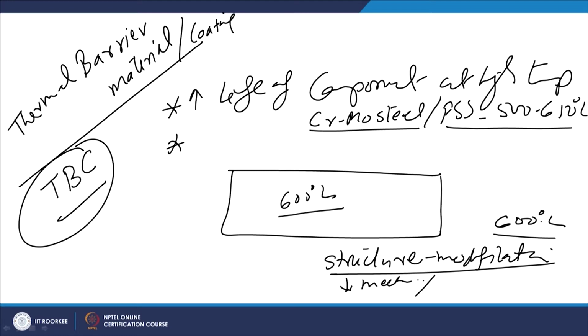Another aspect is that hot flue gases, if they are passing over the surfaces of such components, then a reduction in hardness at a high temperature facilitates the material loss from the functional surfaces, which in turn causes wear. When these components are coated at the surface with thermal barrier coating materials, the effective component temperature is reduced.